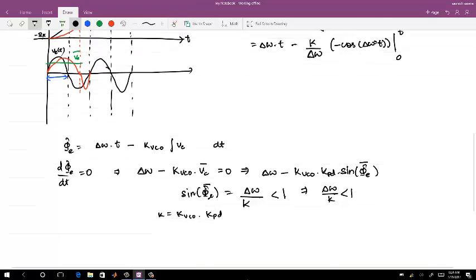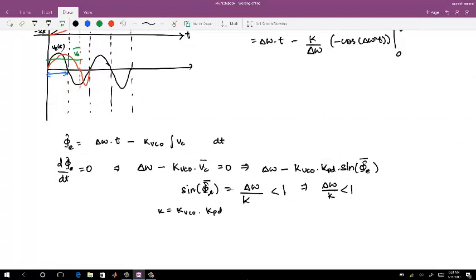So normally, if I come and ask, let's say for example I have delta omega where there is no limit on the frequency error to begin with at time t equals 0. So let me just say that at t equals 0, omega in minus omega out, omega 0, which is delta omega, there is no limit on delta omega, it's upper bounded by infinity.